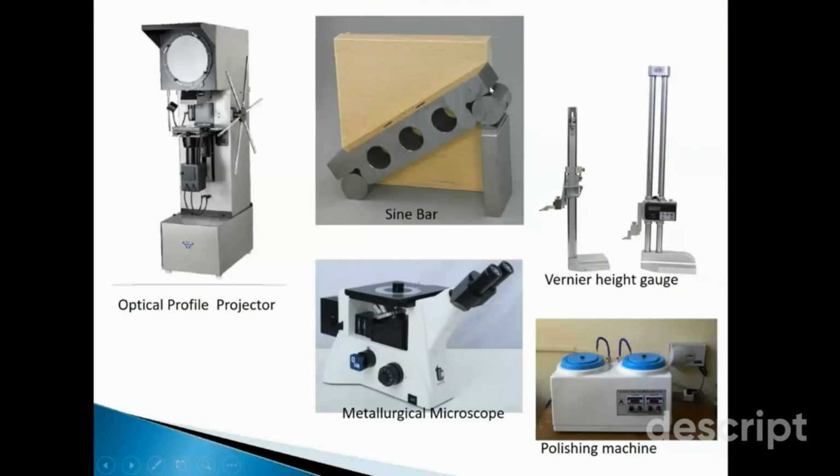We have this particular instrument or device called a sine bar, and you see that this is made up of a very highly wear resistant high carbon high chromium stainless steel, and it has two cylindrical rollers which are attached onto this surface. One surface rests on the base and the other surface rests on this rectangular block, which is your slip gauge. This gauge I was talking about has this shiny surface. This surface and the bottom surface are both parallel to each other, and all these surfaces are highly flat and have a high degree of smoothness.